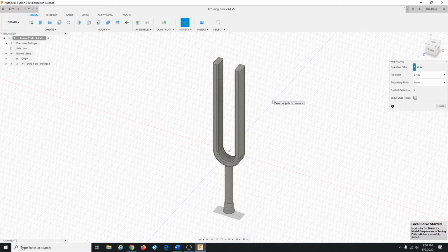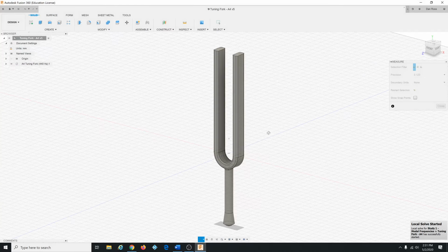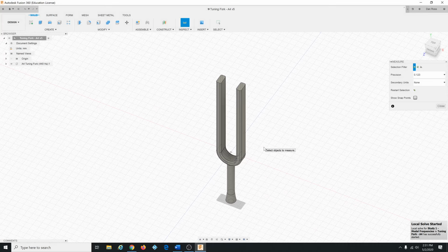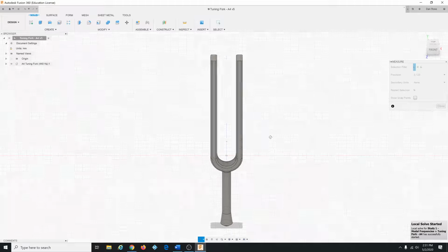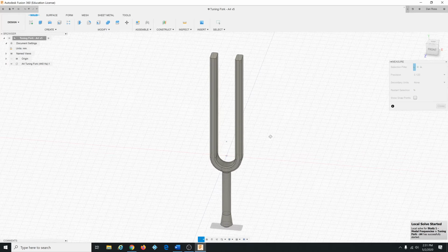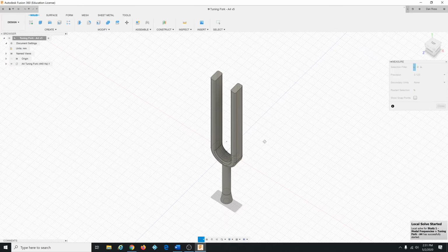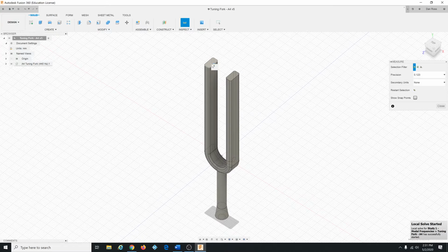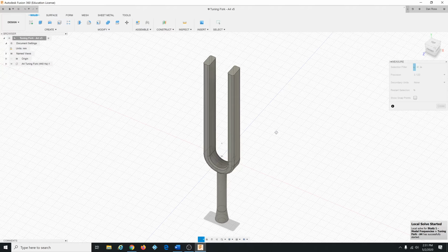Like you might have a motor that's running at the resonant frequency, whatever that frequency is. Or you might have some other thing that's happening on the machine that if it happens to be at that resonant frequency, then that's bad. The whole machine will shake and you'll get vibration. So power tools, any kind of machinery, you want to check for resonant frequencies and make sure that the machine is not resonant at the frequency that it's going to operate at, basically. Otherwise, it'll vibrate excessively. So it's pretty useful, pretty powerful stuff.